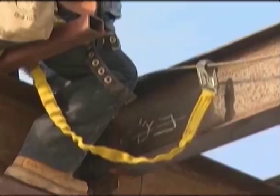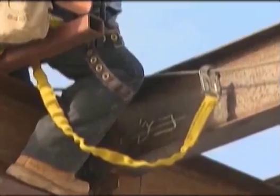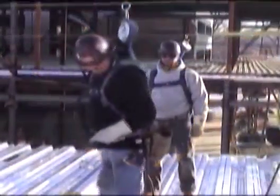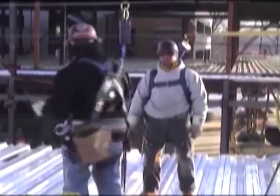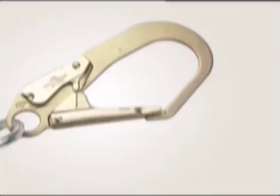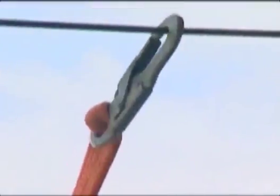The connector is a device which is used to connect parts of the PFAS and positioning devices together. D-rings and snap hooks must have a minimum breaking point of 5,000 pounds. They must be proof tested to a minimum breaking load of 3,600 pounds without cracking, breaking, or suffering permanent deformation. Snap hooks must be of the locking type.